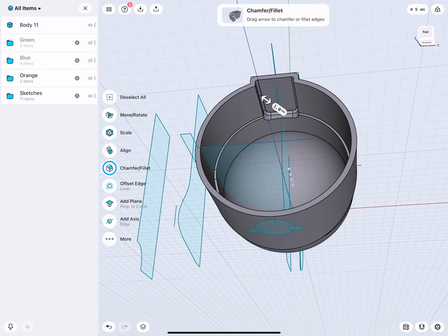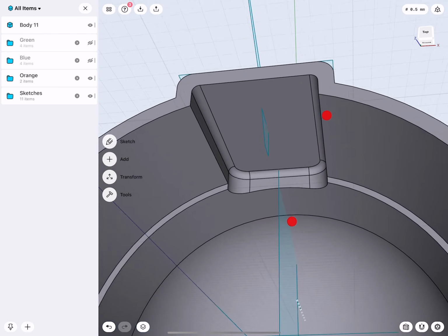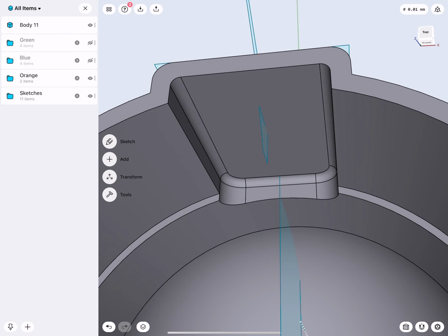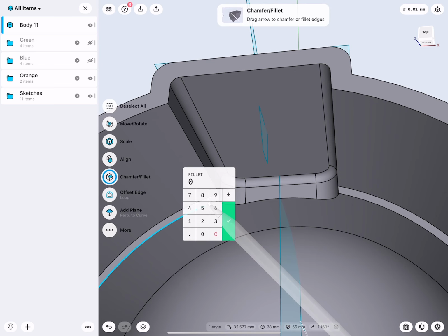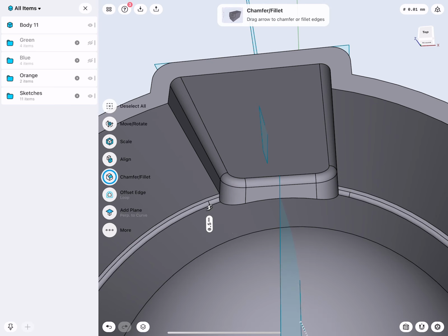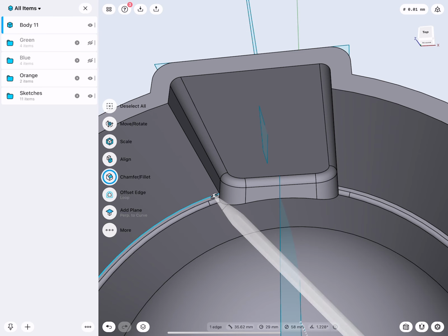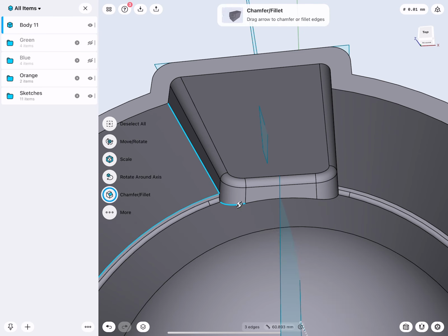In my case here, I will actually skip this because this could be quite time consuming. It's a detail work. I'm not going to spend too much time on it, but you saw how I rounded this inner edge. I can also round this edge, and then all these edges, again trying to follow logical filleting strategies, I can start adding.